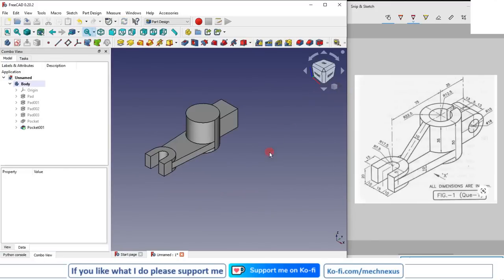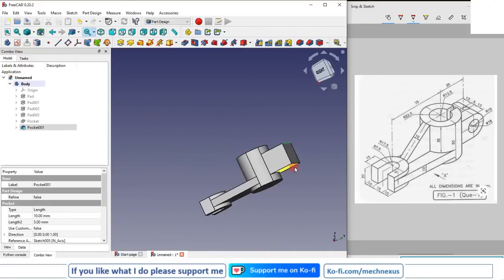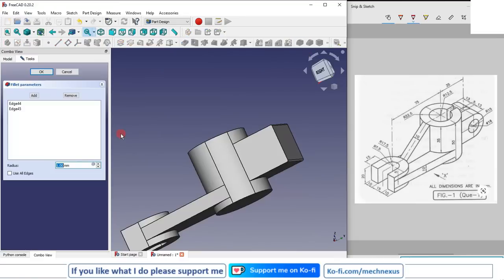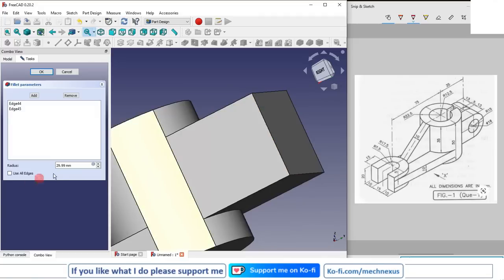Now I will switch to the isometric view. Now I will select this edge and this edge, and I will go with a fillet, and I will give 30 here. So in FreeCAD it does not take the rounded value, so we will give 29.99. Sorry, it is a 15 radius.